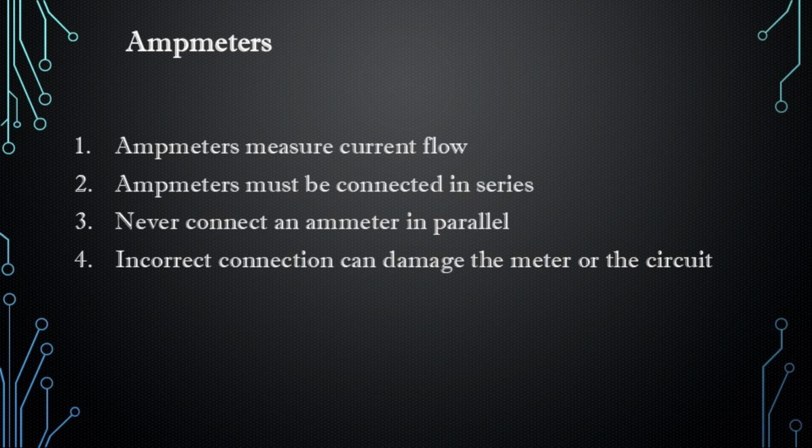If an amp meter is connected in parallel, especially across a power source, the meter's low internal resistance can create a serious fault condition that can damage the meter, damage the circuit, or create a dangerous situation. So one of the most important memory rules in electrical diagnosis is this: voltmeter in parallel, ammeter in series. If the student locks that in early, he avoids a whole lot of mistakes later. And honestly, some expensive ones too.